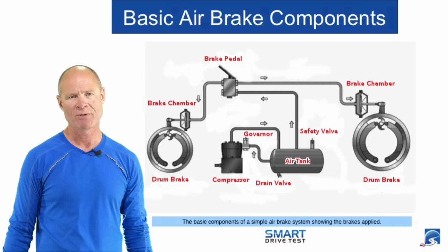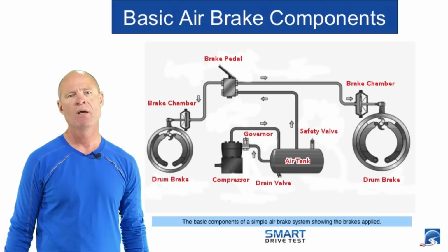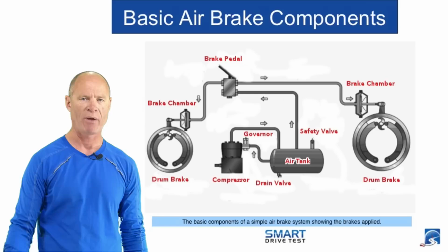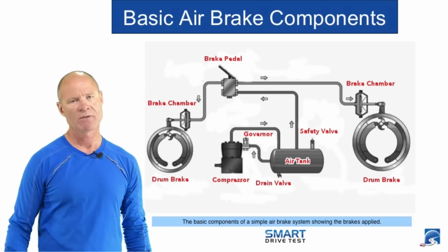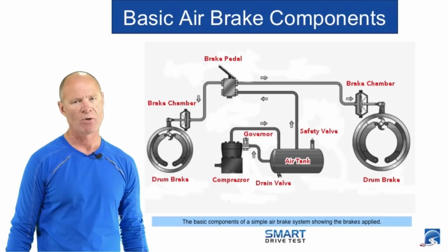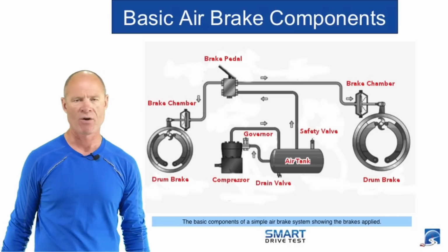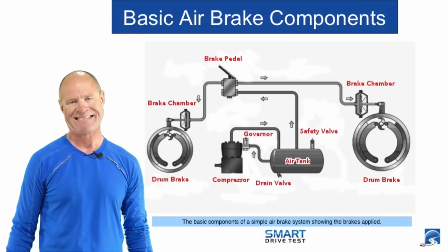They pretty much became obsolete when gasoline engines were replaced by diesel engines. Gasoline engines created vacuum, which made air over hydraulic brakes plausible because they could use the vacuum from the gasoline engine to power the master cylinder. Once diesel engines took over, they no longer created vacuum, and it was no longer feasible to have air over hydraulic. So air over hydraulic became obsolete, and they went to a completely air brake system.